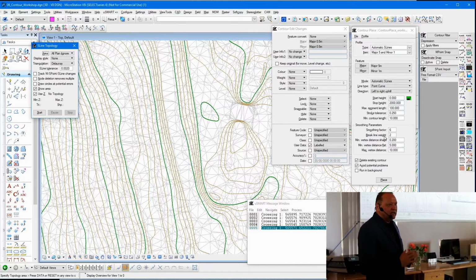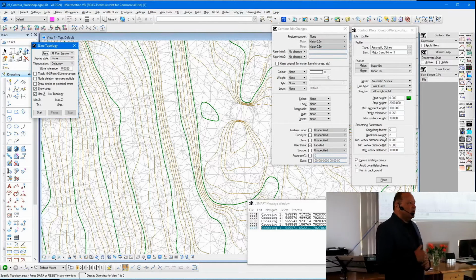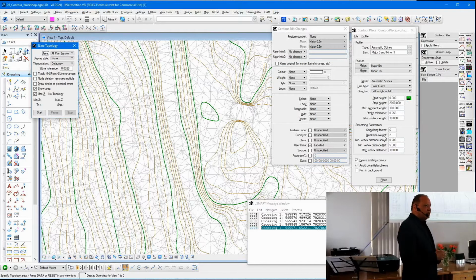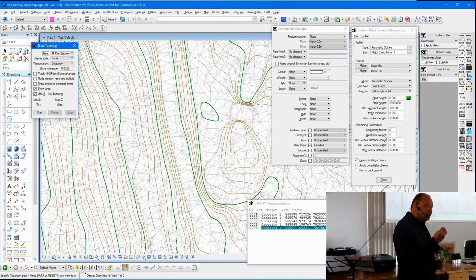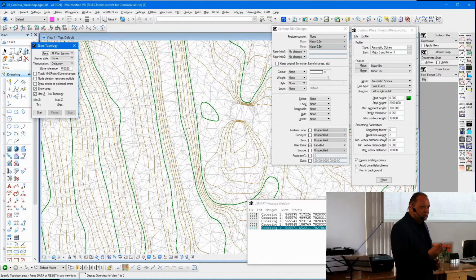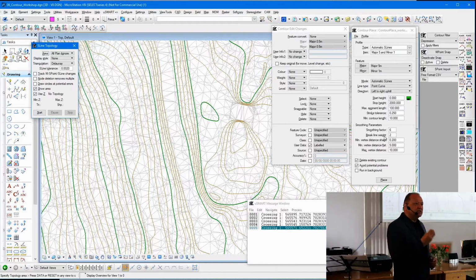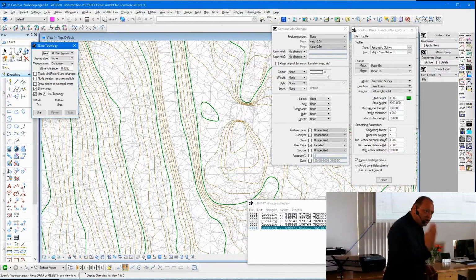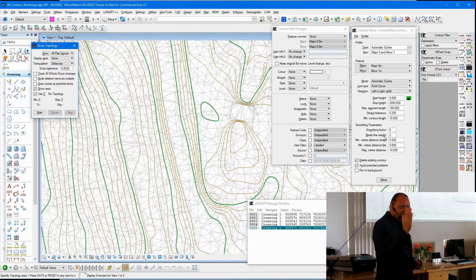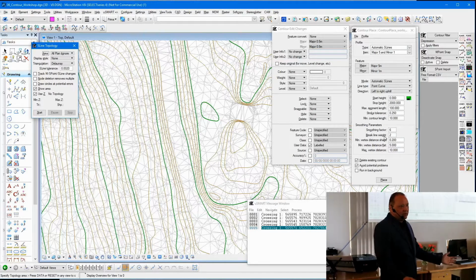and you can do volumes, and you can shade them, and you can do these kind of things. But now, obviously, we're adding the features for each. So you could literally identify, during that process, every single break line if you wanted to, and have different features of break lines. So you might say, for example, now you can do the same thing, but you'd have to do it in an individual process. Whereas once you've got features, you could say, okay, my road edge has a weighting factor of 2, but my stream has a weighting factor of 3, for example, or whatever, or maybe probably the other way around.